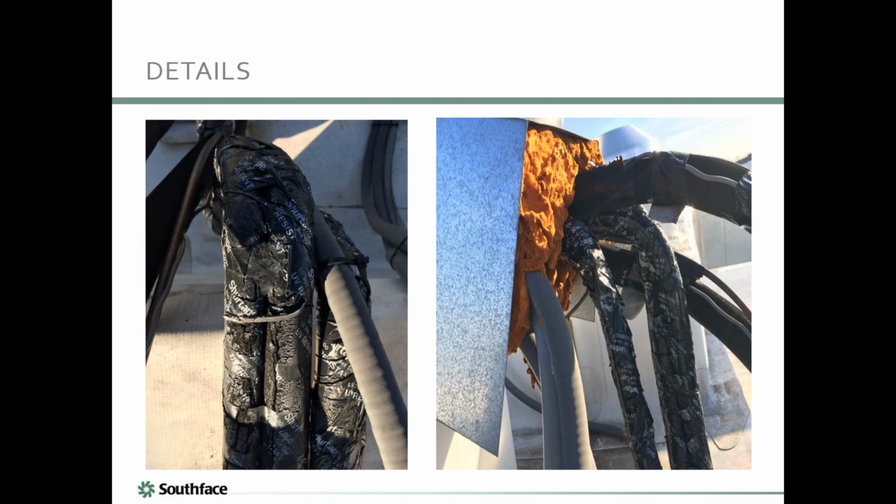I tested last week a multifamily building, and they had not sealed the chases that allowed the refrigerant line sets to run from the roof down to the air handling closet in each of the individual units. They also were running bath exhausts and kitchen exhausts through that mechanical chase, and we're getting 4,000 CFM blower door numbers on these 1,000 square foot units. Why? Because there's a giant chase open to the outside, all the way up through the roof of the building. So the common culprits, I guess, even if you didn't do a blower door test, you could probably make a safe assumption that these are good places to go look for air leakage.